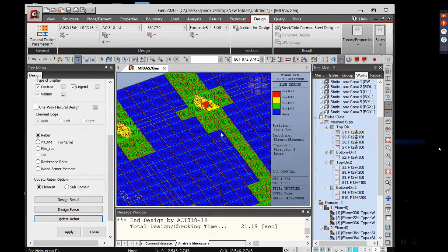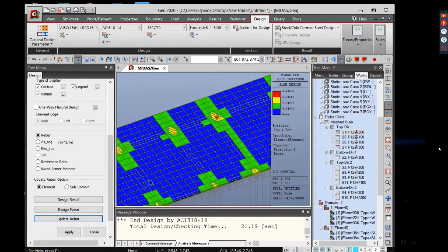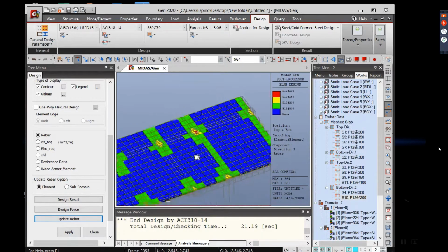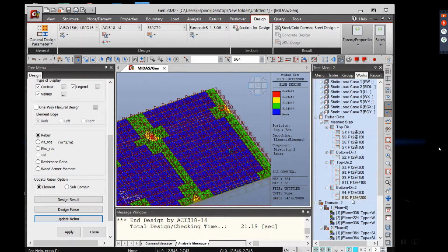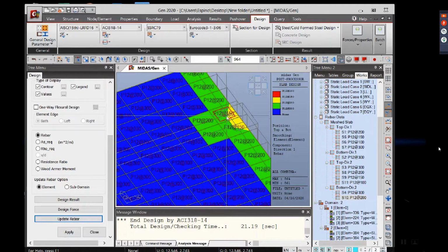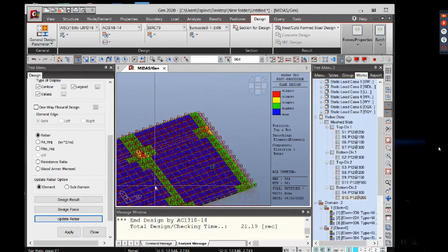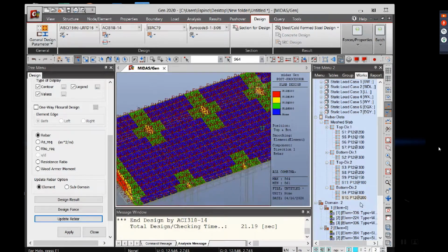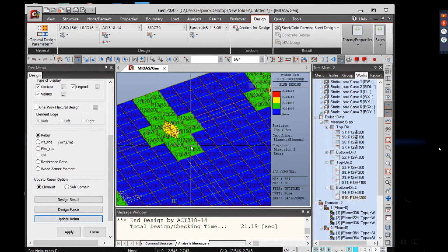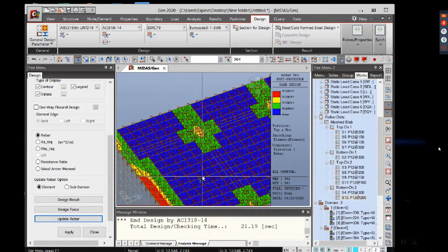After doing that, let's say I want to change a portion of this slab. We have a portion of slab which has 200 millimeter spacing. This portion actually requires us to have a spacing of 200 mm for the bottom direction along direction 2. Direction 2 is actually along the y direction.